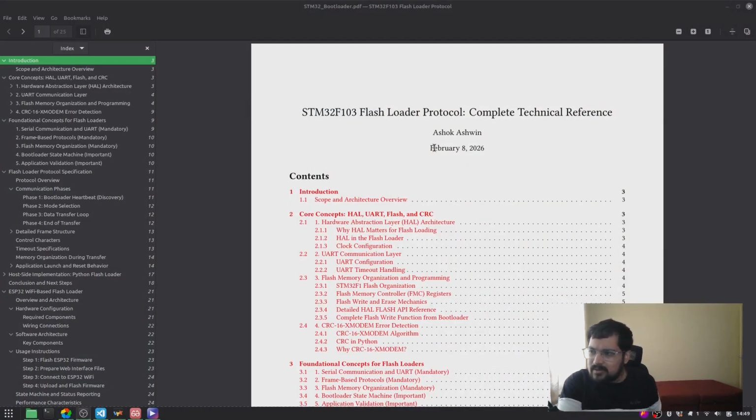In the previous video, we only saw bootloading, but we have not seen how the bootloader also has the capability to write into the flash. We are going to enable that feature via UART. There's a custom UART protocol we are going to write that reads in bytes, and then we send the bytes into the flash memory. How we achieve it, and how we make sure we do so in an error-free fashion, will form the rest of this series.